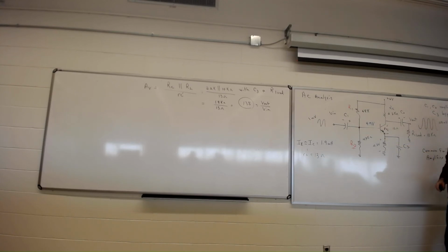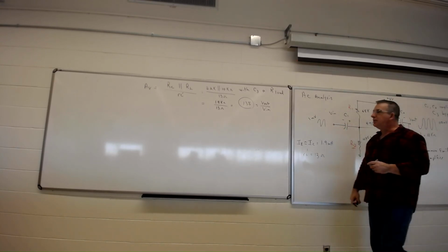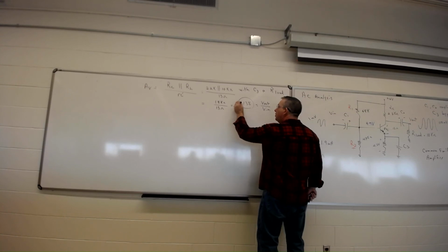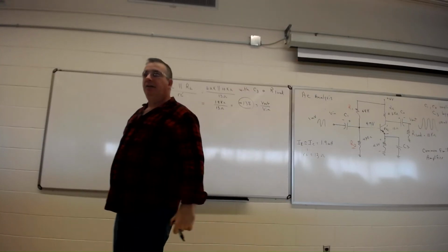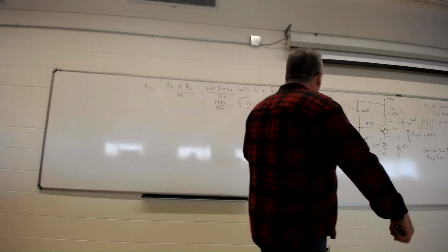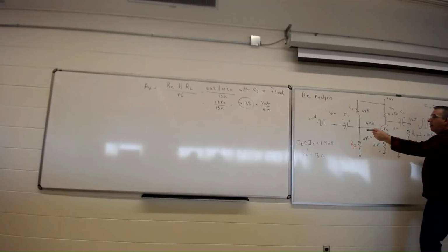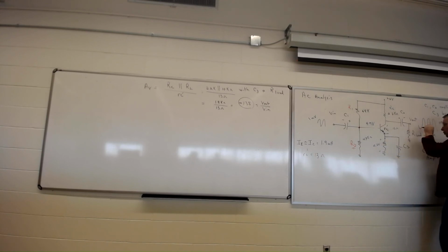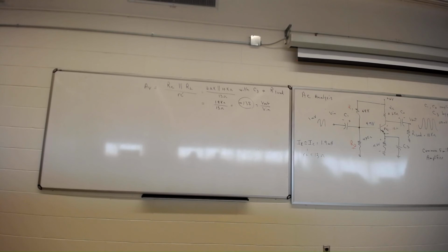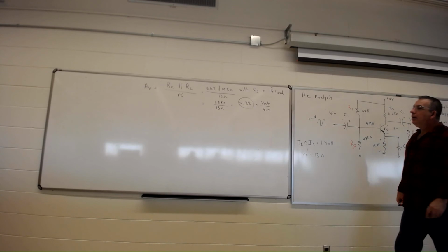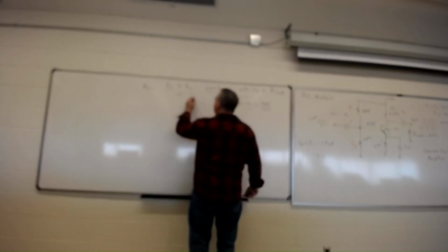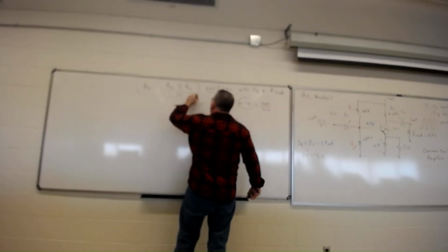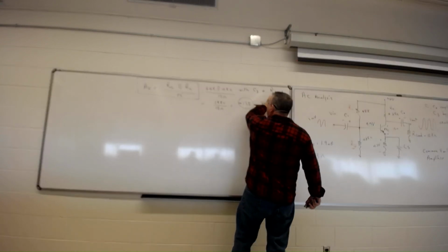In fact, as I said, whatever comes in here also gets flipped over 180 degrees. So in justice, we should say that the gain is minus 138 on this particular type of amplifier. What comes in at the base, compared to the collector, when you go up, the signal actually goes down over here. So there's a 180 degree inversion from base to collector. All right, so that's the equation. This equation up here is the equation you would use if you have C3 and R load.